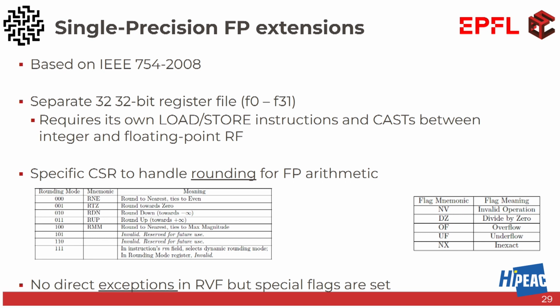Now again, in the topic of sub-extensions, there is a Zfinx sub-extension of the floating point extensions that says, what did we say before? What is very expensive in CPUs? A register file, right? Do I need to add one? Maybe not. If my code is not really operand heavy, it doesn't require a lot of operands, then I can share the register file together with the integer.